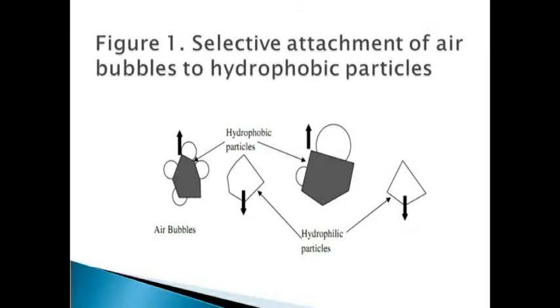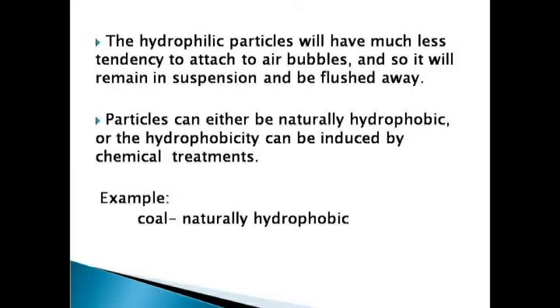The froth layer that forms on the surface will then be heavily loaded with the hydrophobic mineral and can be removed as separated product. The hydrophilic particles will have much less tendency to attach to air bubbles, and so they will remain in suspension and be flushed away, according to Whelan and Brown, 1956.